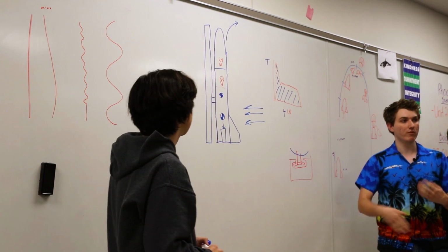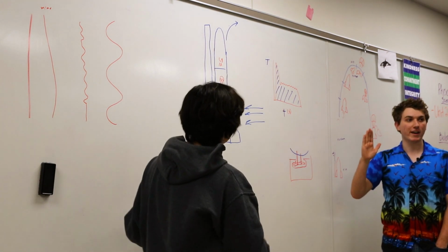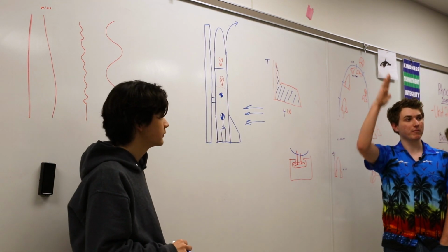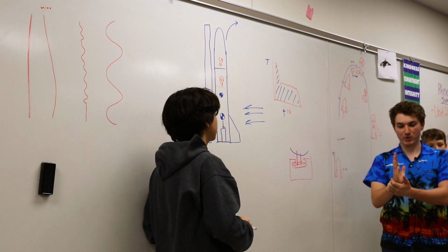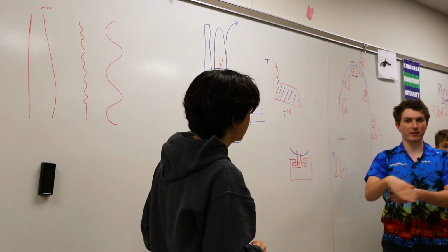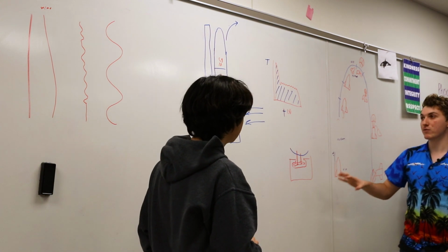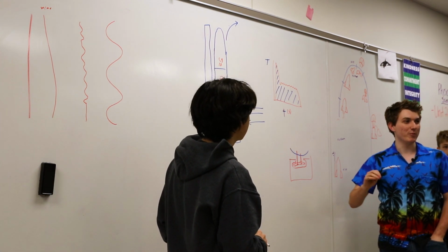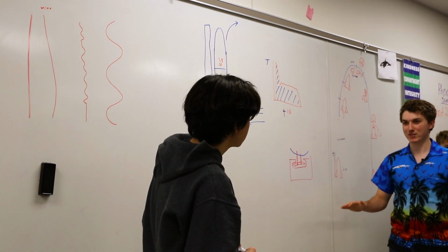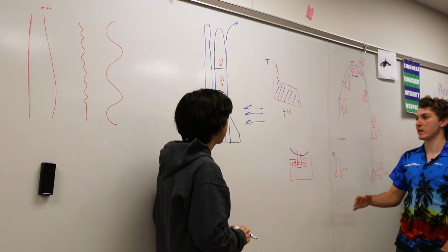So you need time to build up velocity, build up speed, so drag can act on the rocket so it points straight. Because if you just launch with no rail, it could go sideways. Who knows what will happen. We use a very long launch rail so that we just don't have to worry about it as much. So we have a lot of time to build up speed.